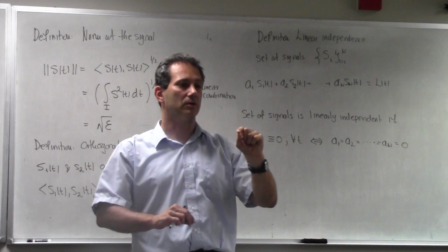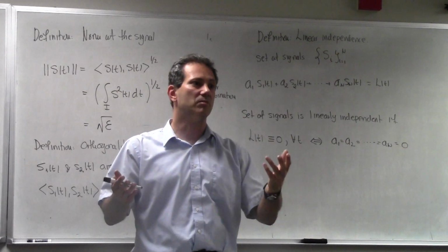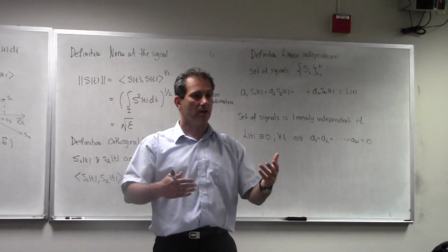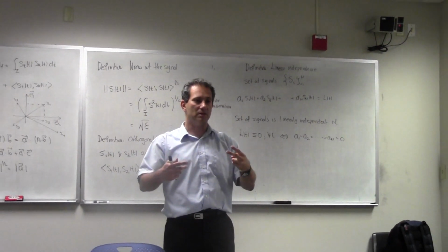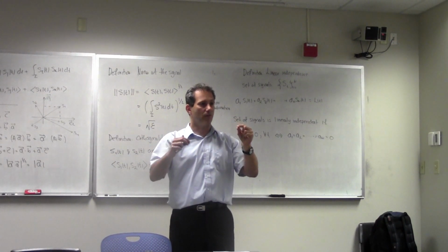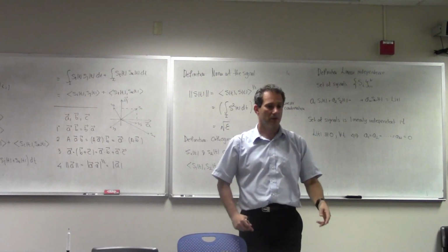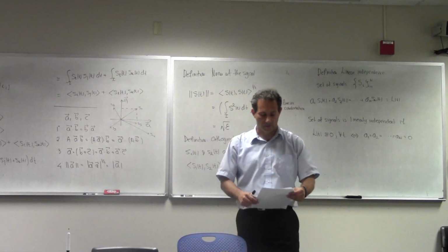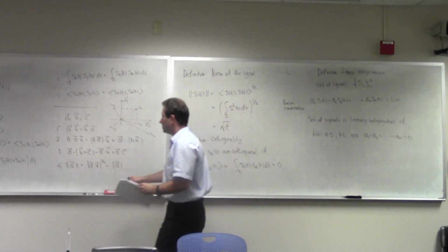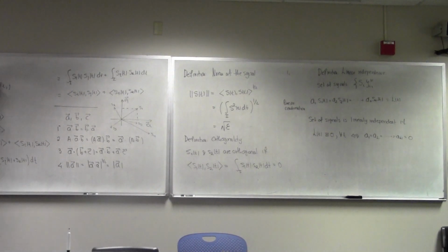We can talk about 2-dimensional signaling, where we have 16 symbols or 16 different waveforms in our signal set. But 2-dimensionality means that each one of these 16 waveforms can be formed as a mixture of 2 other primitive waveforms, which we can call basis waveforms or basis vectors. So let's go through Gram-Schmidt orthogonalization so that we understand this a little bit better.